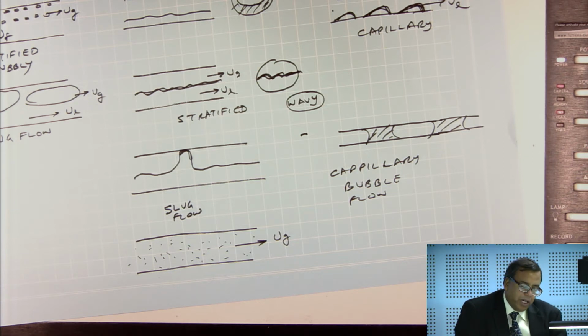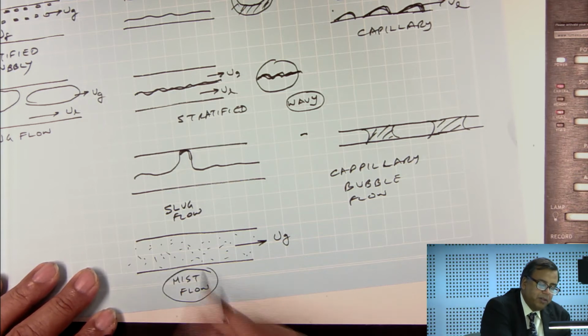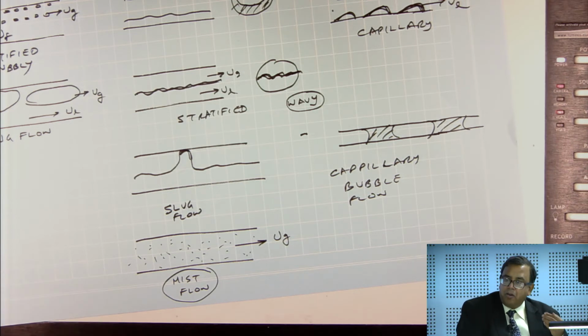Okay. And so that is what is known as a mist flow, and this happens right before the steam is entering your turbine. And one of the things that you have to ensure is this mist is completely vaporized before it enters your turbine, because otherwise it will corrode your turbine blades.